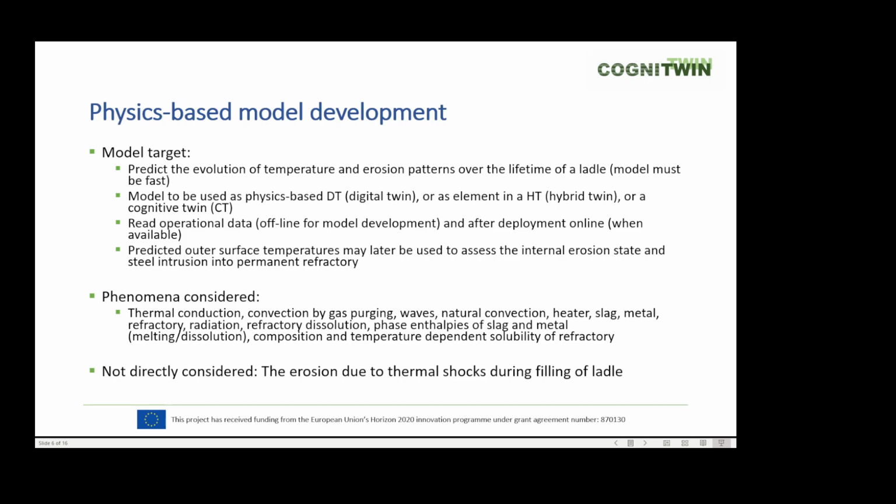We also have to deal with phase enthalpies of slag and metal to handle the phenomena of melting and dissolution. And composition and temperature dependent solubility of the refractory is also an important issue. What was not considered is the erosion due to thermal shocks during filling of the ladle, and also phenomena above the liquid level in the ladle.